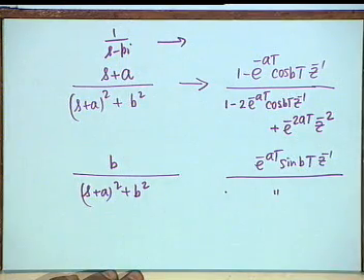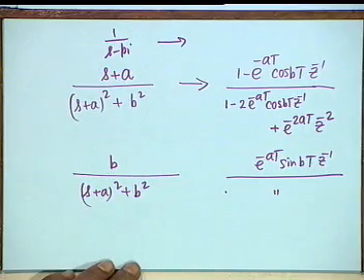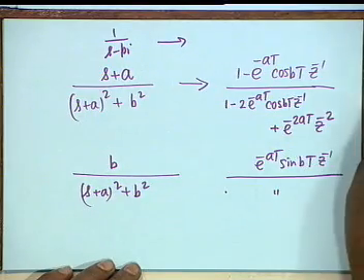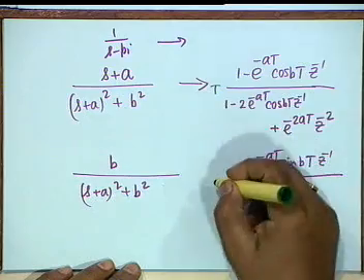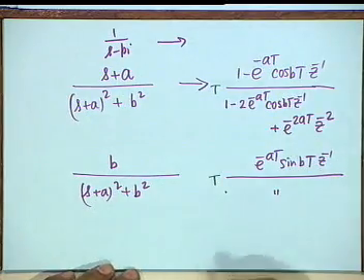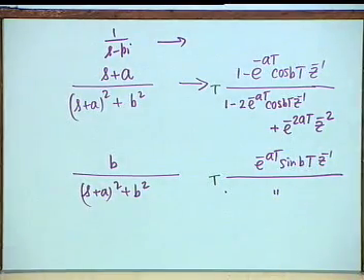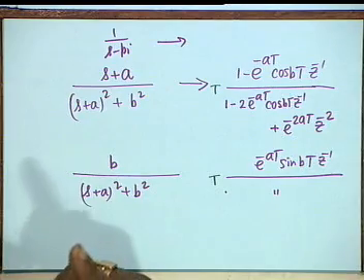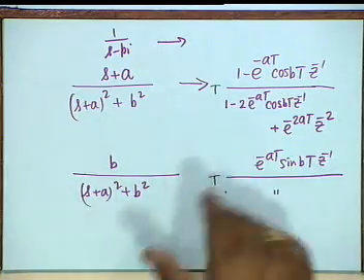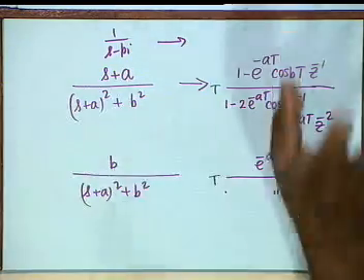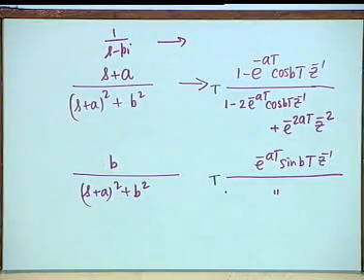Won't we multiply by T? Yes, you have to multiply by T. So, what you do is, you don't do this piecewise. What you do is, you take h of n as capital T multiplied by h_a of nT. Then you expand, and then you take the z transform, obtain this, obtain that, and so on and so on. Okay? So, you don't have to do this every time.